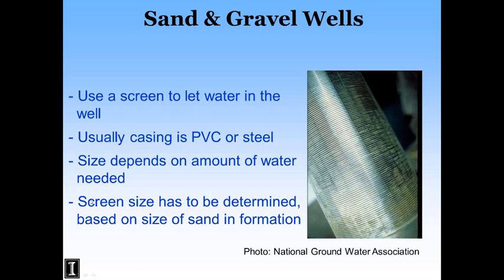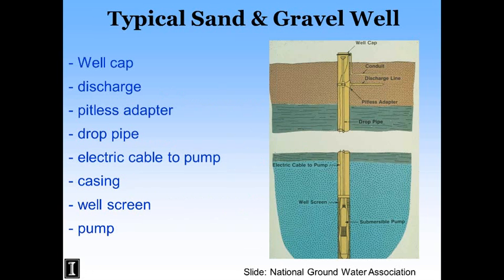And usually the driller will size your screen based on the sand that they pull out of the formation when they drill the well, so they know what size screen to use to make sure that you can get enough water and also keep sand out. And this is a typical installation.